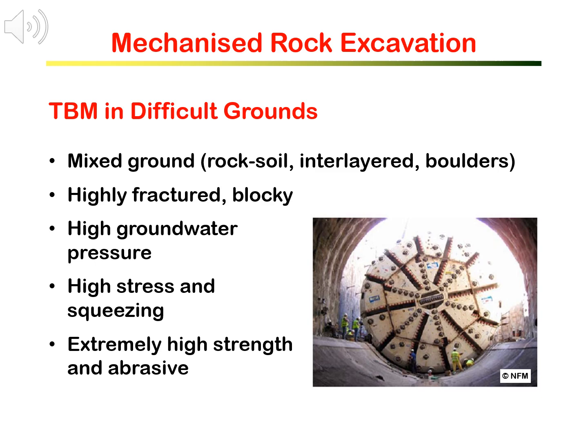Mixed ground, such as rock-soil mixture, rock-soil interface, and rock boulders surrounded by soils. 2. Highly fractured and blocky rock masses. 3. Groundwater with a high groundwater pressure and a high water inflow. 4. Tunnel subject to very high stress at great depths and the ground is squeezing.